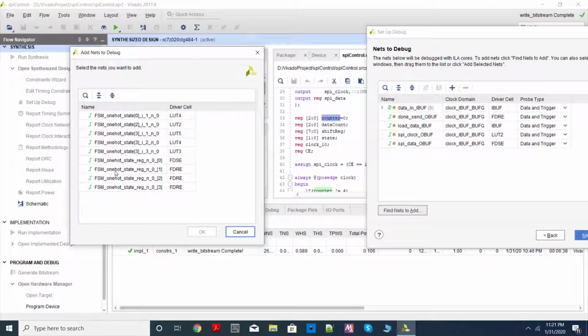I don't know, have you heard about it before? In digital design, I hope you have heard of one hot encoding. That means in the state variable, only one bit remains high and everything else is 0. You can go and check it up. So it found there is a state machine, and the best way to encode my state machine is using something called one hot. That's what it has done.